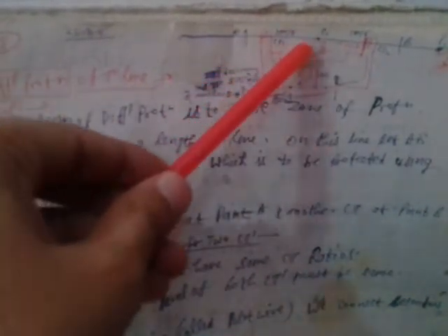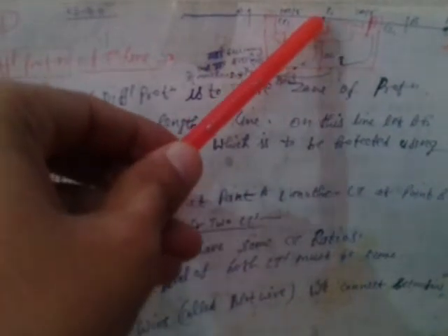You see here, what I said, I repeat once again. In case number 3, let us say a fault occurs at point P2. This point P2 is within the protected zone AB, so the relay should operate. That's what we desire, right? So suppose the fault current is 1000 ampere.